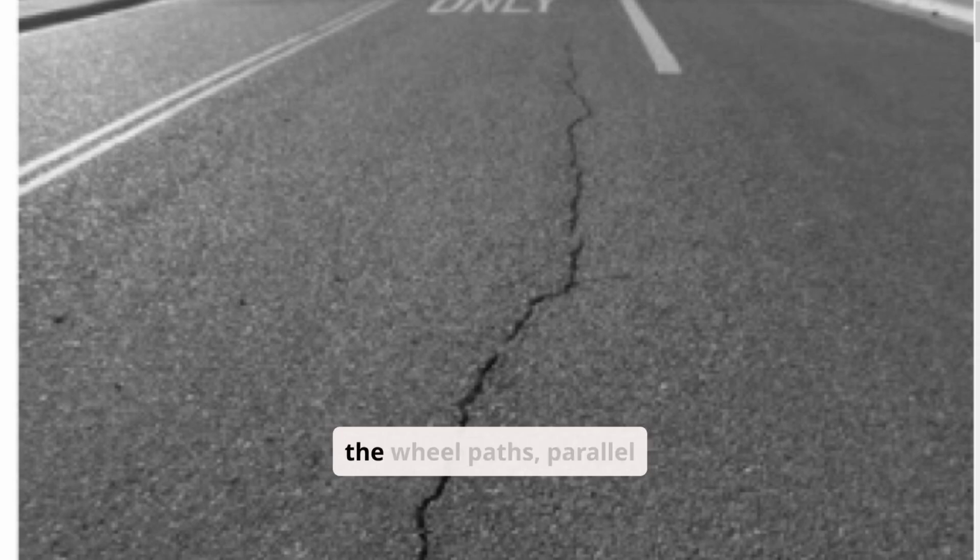Understanding top-down longitudinal cracking. Longitudinal cracks near the wheel paths, parallel to the centerline of the roadway, are called top-down longitudinal cracks or longitudinal cracks. The figure shows the photos of top-down longitudinal cracks. Crack initiates at the surface of the asphalt layer due to repeated tensile and/or shear strain caused by wheel loading, AASHTO 2015. It can also develop along the construction joint between adjacent passes of the paver or at a location that corresponds to the center of the paver.